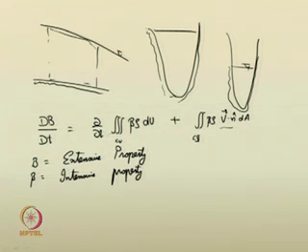Then you have the volumetric integral as well as the areal integral. If you apply this to the control volume of the fluid in the gradually varied flow phenomenon, let us start with conservation of mass first. Your extensive property is mass.